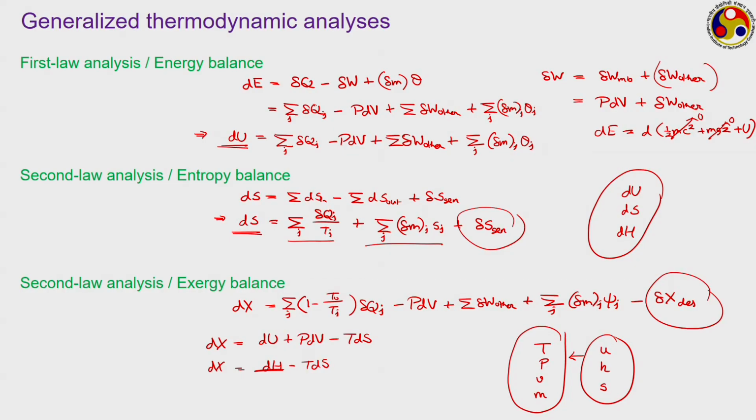And a second thing of importance here is that, truly speaking, we are not bothered about the absolute value of U or S. We are trying to identify the change in internal energy or change in entropy or maybe the change in enthalpy. So, what we are trying to develop now are relations not to have perfect values of these quantities, rather to get the expressions for the changes in them, that is changes in internal energy or enthalpy or entropy, and similar parameters, which we are trying to develop in this particular module.